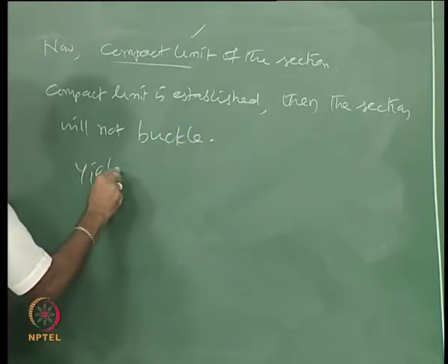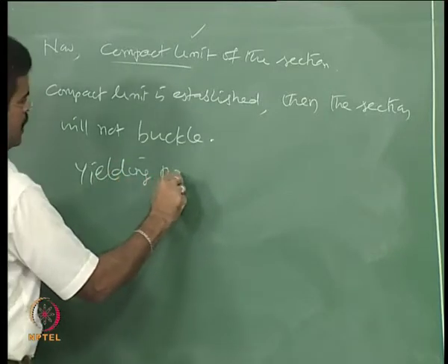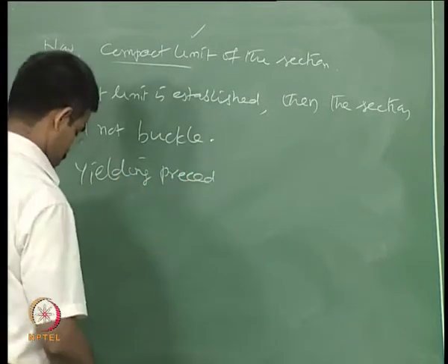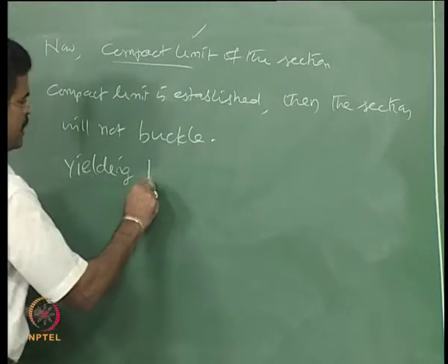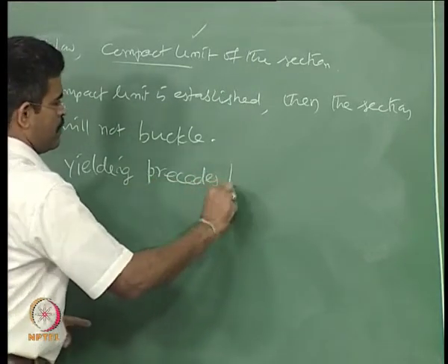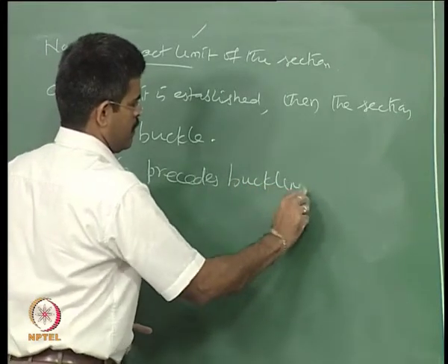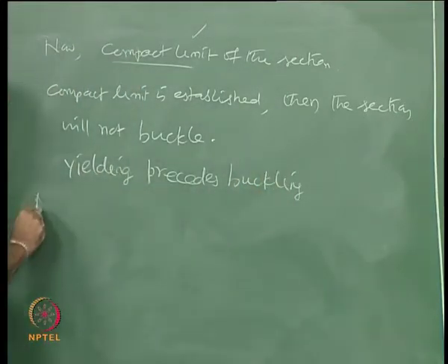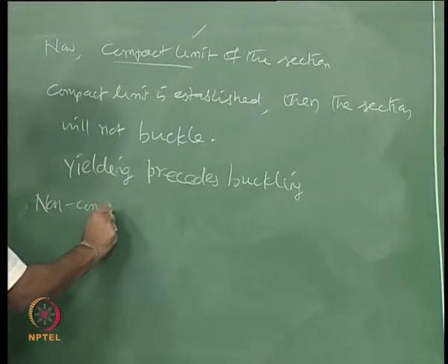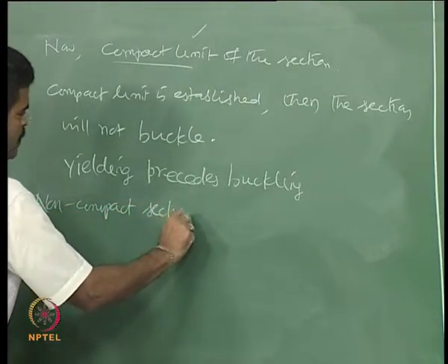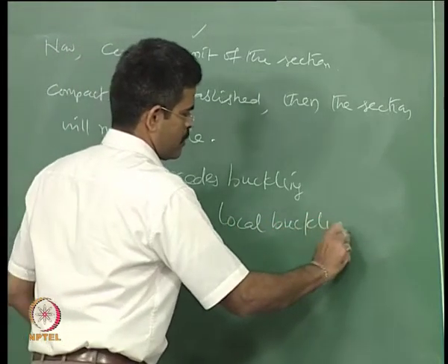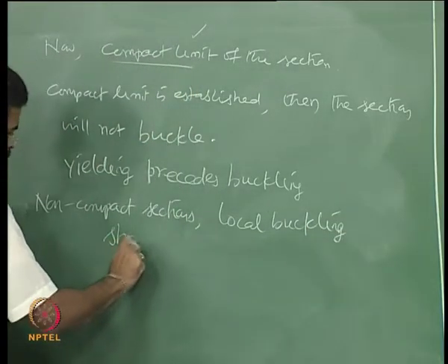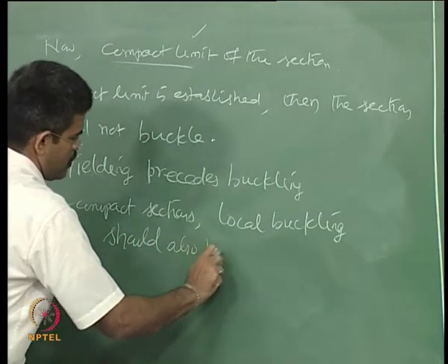So yielding precedes buckling. However, for non-compact sections, local buckling should also be considered. That is the catch here.